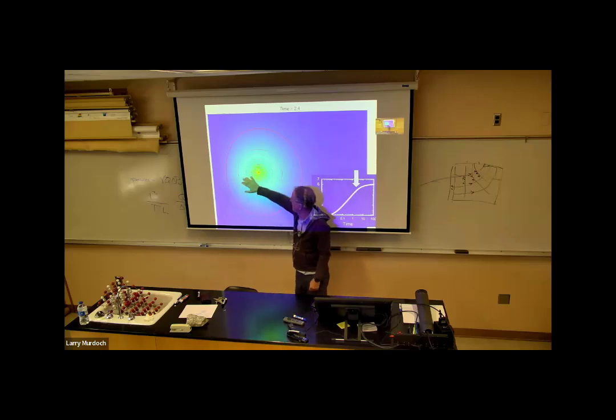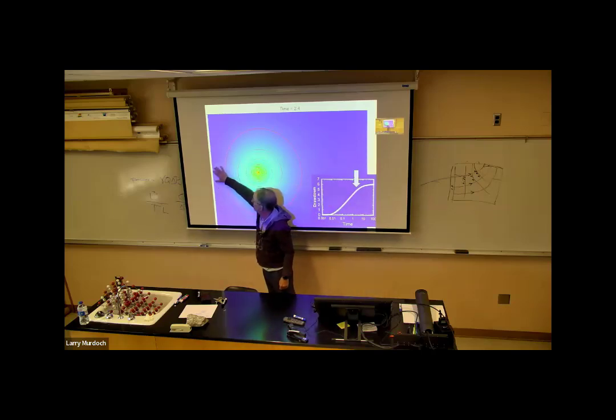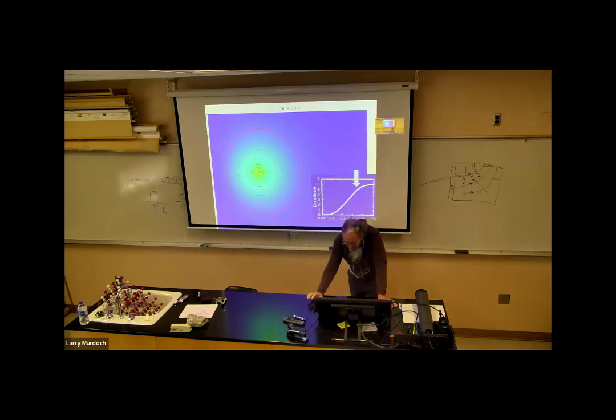What's happening is water is coming out of storage here because we're dropping the head. But when the drawdown starts to approach here, we're going to have water coming out of this boundary and flowing towards the well. And what you can see happening here is if we extend this straight line out, at this point, time equals 2.4, we're starting to curve and drop off of the projection of the semi-log straight line.